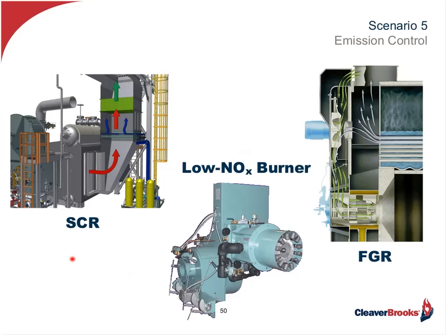Normally an uncontrolled gas burner will generate about 120 parts per million of nitrogen oxides. And that's what we're concerned about, because NO and NO2, nitrogen oxides, are the precursor to smog, to bad ozone, if you will. So we want to get rid of that. Low NOx burners will take that NOx, just by themselves and firing into the right combustion chamber, into the furnace, reduce it from 120 parts per million down to 60, 40, maybe even 30 parts.